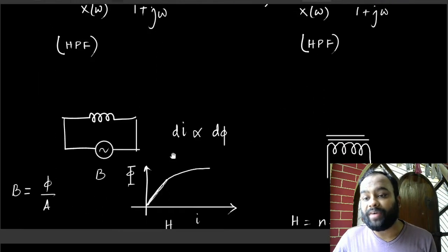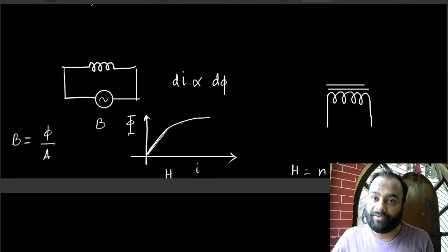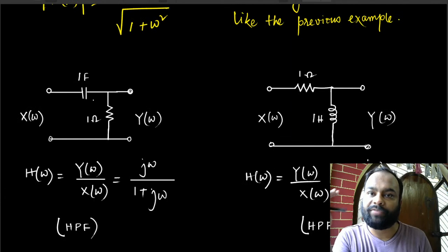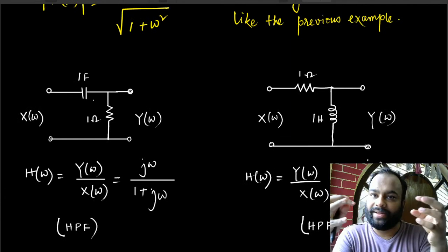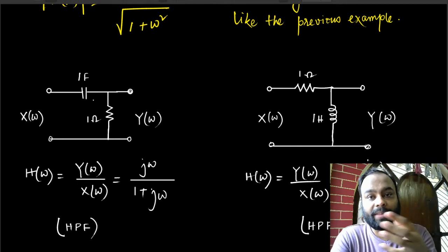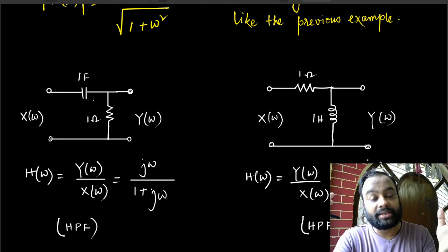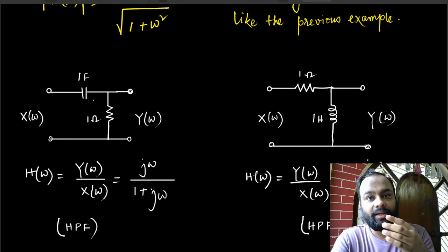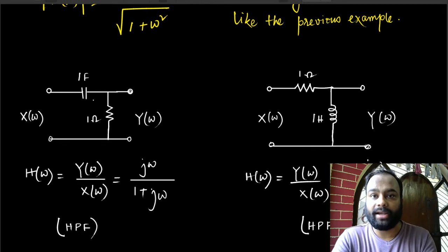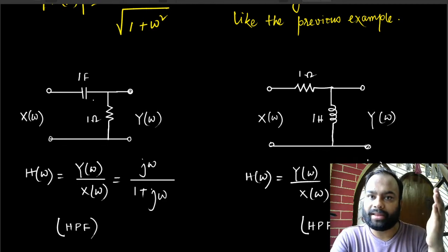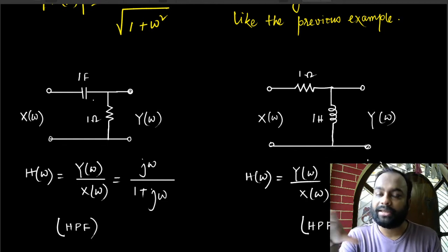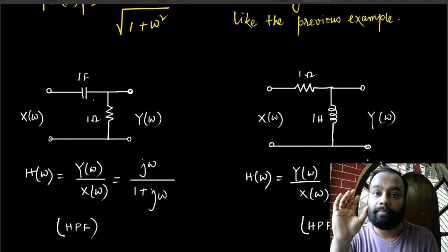All right. And also, if I increase the frequency, then again, the behavior of an inductor degrades very quickly. That also happens with capacitors. If I increase the frequency of a capacitor, then what happens? All the internal resistance in the material of the capacitor comes into effect. Subsequently, with higher frequencies, the capacitors start acting like a resistor. Then with even higher frequencies, capacitors start acting like inductors. Mind-boggling, right? The capacitors we are considering to be capacitors, with high enough frequency, act like resistors. Then at even higher frequencies, capacitors themselves become like inductors.